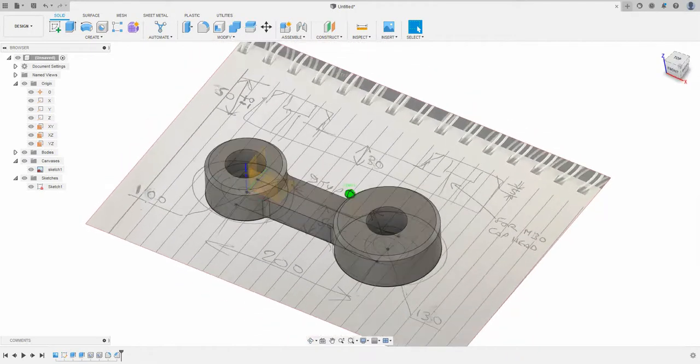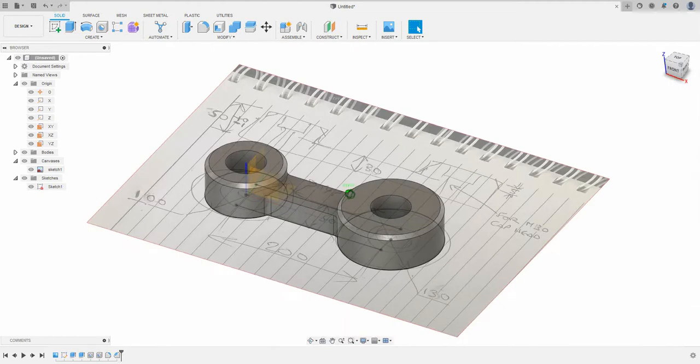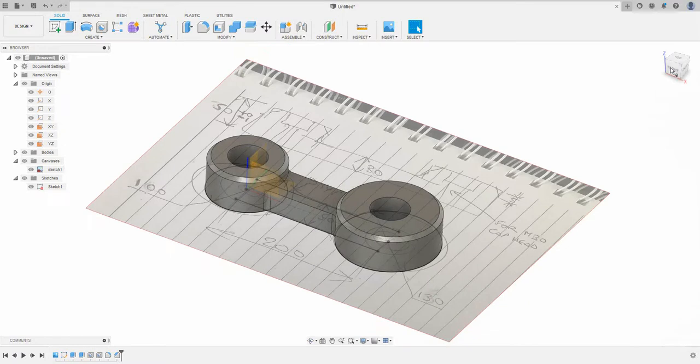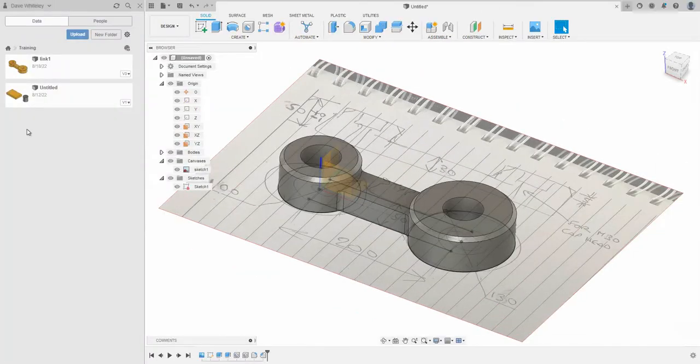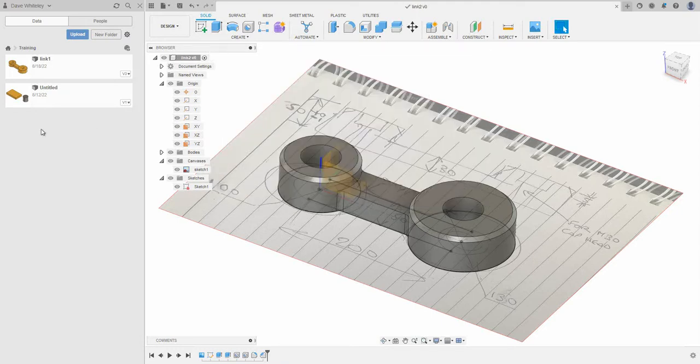We'll do a stress test on this next, and we'll machine it afterwards. Nothing else to see on here. That's all finished. We need to save it, of course. So if I click on the data panel button at the top left of Fusion, that brings back my project browser. Up the top here, the file pull down menu, go to save, give it a name, click on save. We'll worry about working with projects and folders in a future video.